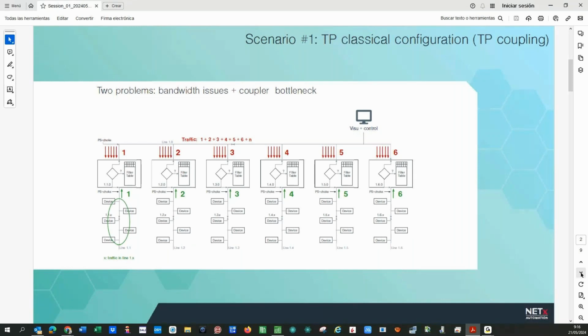The access method of these software packages typically uses the Falcon driver that KNX provides. Falcon driver means just one point of connection to the system. So in a multi-line project, it has to be decided where that connection point for our supervision system will be.